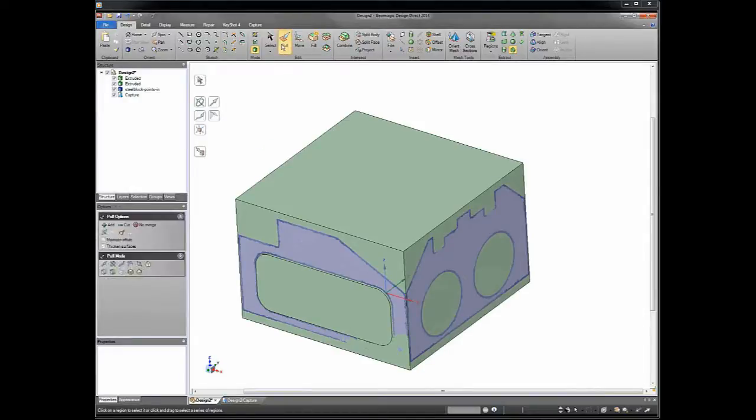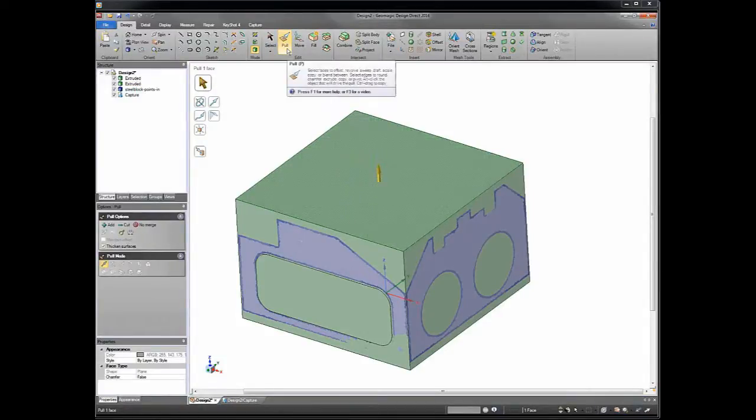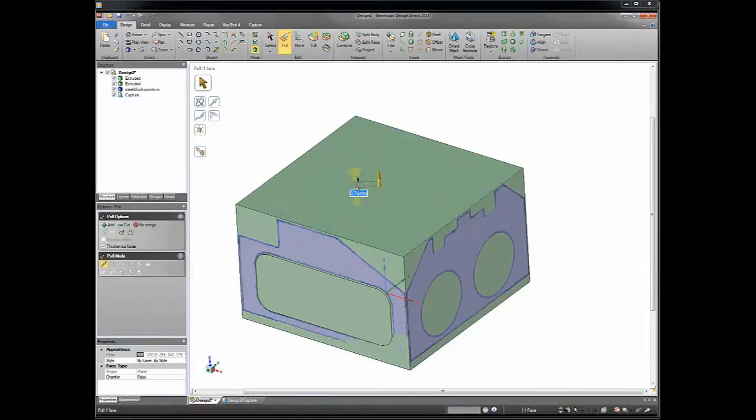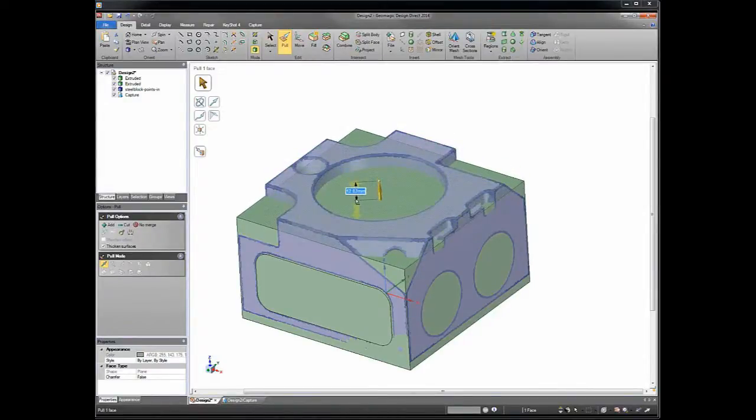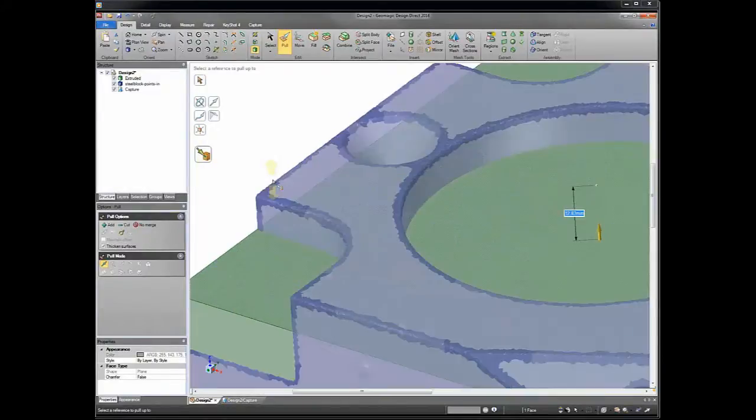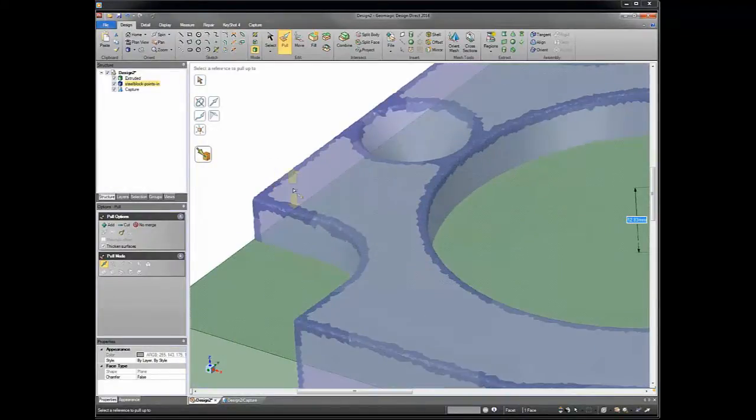Now we're going to step out of one of the Geomagic tools and use one of the native SOLIDWORKS tools, in fact, probably their star tool, which is called Pull. And what Pull does is direct modeling at its most essential. It's the ability to click and drag on a face. And with the little bit of latency in the webinar, it won't be quite real time. It's much more fluid when you're not doing it over the web. But what you can do is move that face, and more importantly, I can choose to move that face up to any picked point.